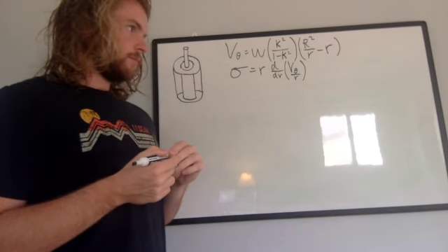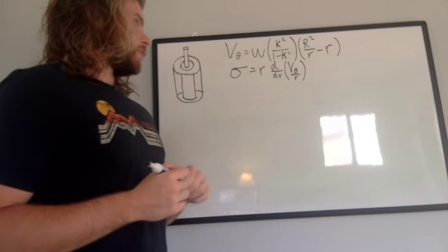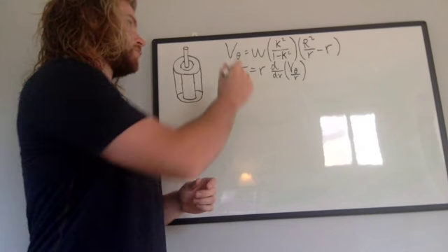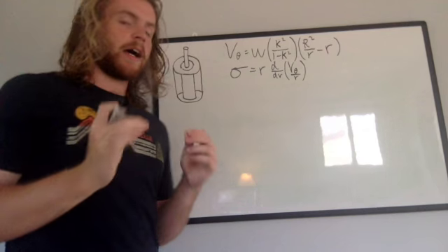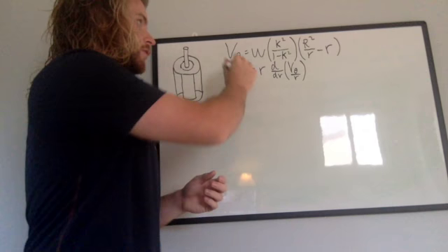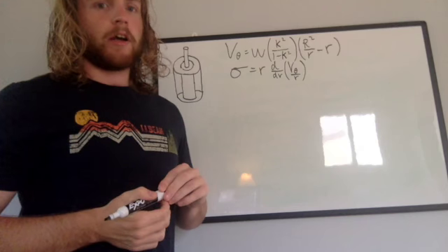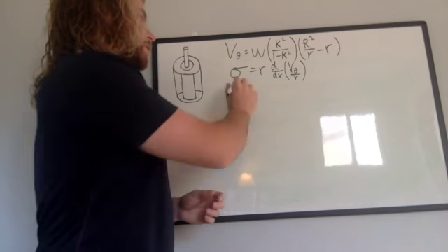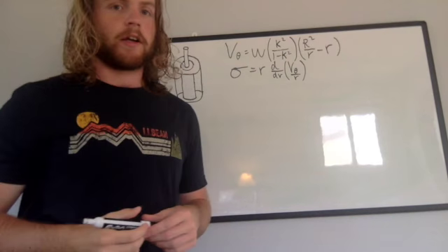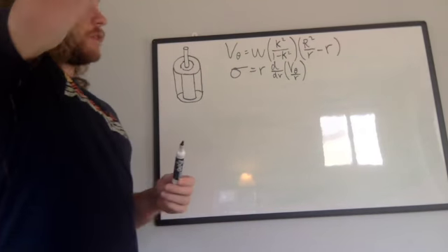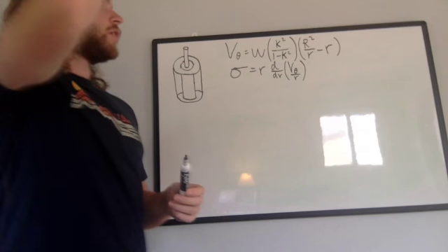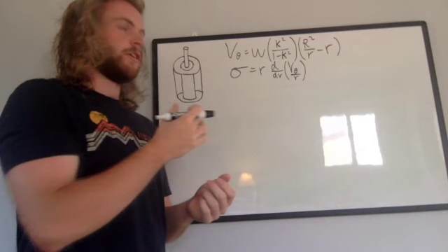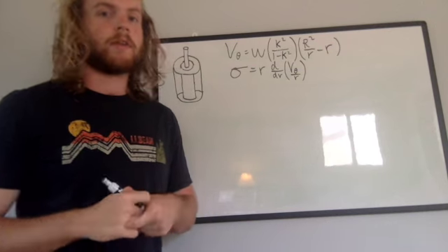And yeah, so basically the equation that is going to be used to describe the speed in the middle parts where it's not touching the surface is going to be right here. That is going to be our velocity profile equation right here. And this is going to be our shear rate equation right here. And we're going to be using these two equations to prove that the torques on the inner cylinder and the outer cylinder are going to be equal, alright?